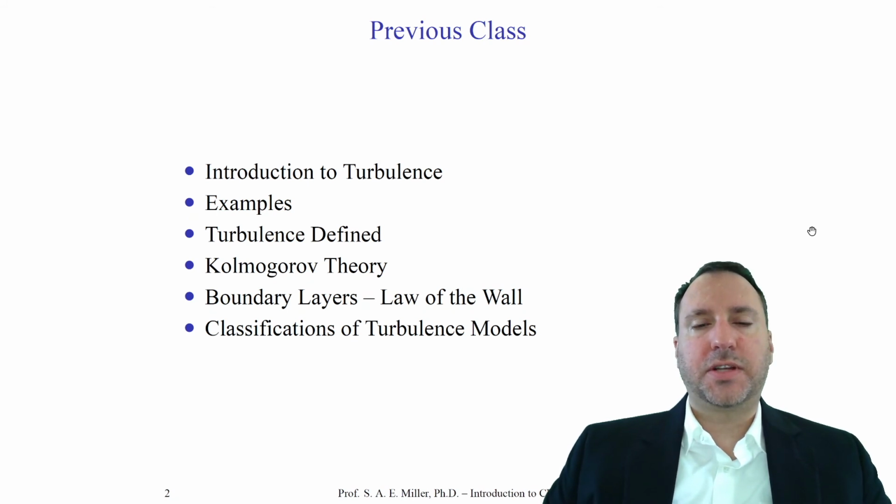The second case we looked at, of course, is the turbulent boundary layer. In the turbulent boundary layer, we looked at the law of the wall. And of course, we discovered that there's some sort of self-similar collapse, if you will, with a few empirical parameters for most, if not all, turbulent boundary layers. The exact form of these equations is argued in the community. Nonetheless, it can help us estimate the number of grid points we need near the wall to resolve the turbulent